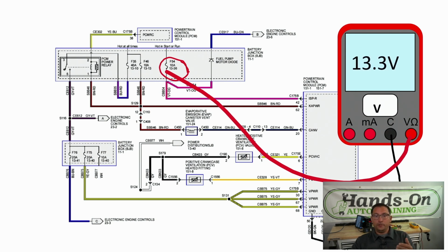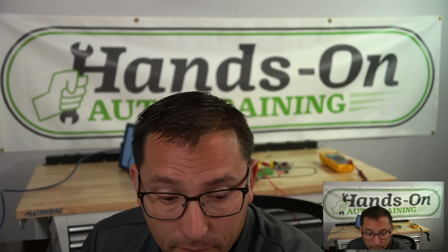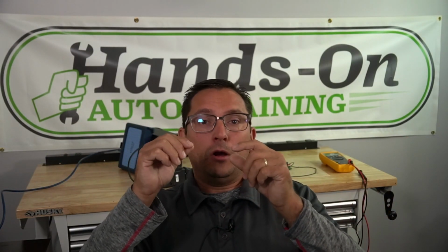Well, 13.3, right? All right, so moving right along, I go to the back side. We had to flip this fuse block up, and over here I had 12.4 volts. So just so you all know, right in here, there was an issue somewhere. Now, I removed that fuse and put that fuse back in, and I hate to tell you that the problem went away. The fuse had a very odd brown tarnish to it.